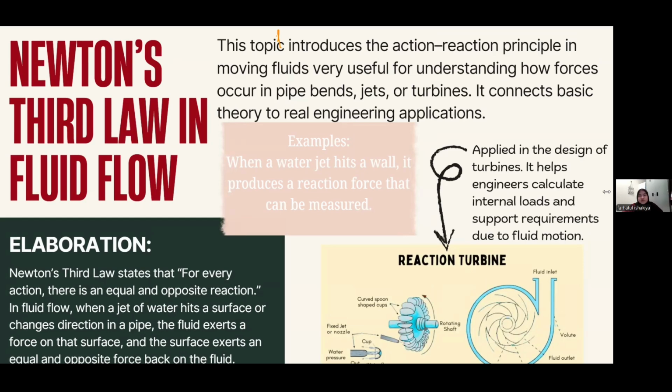moving fluids, very useful for understanding how forces occur in pipe bends, jets, and turbines. It connects basic theory to real engineering application. For example, when a water jet hits a wall, it produces a reaction force that can be measured. Elaboration: Newton's third law states that for every action, there is an equal and opposite reaction.